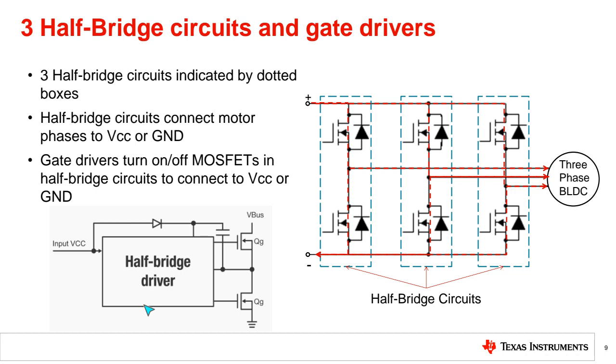It is very important. This is a short circuit position. If you send an on message here and an on message here, it will be a short circuit. If you send an on message here, it will be zero. It's complementary working. You will add a NOT gate. If you generate one for another input, you will use a NOT gate in order to generate a zero signal.